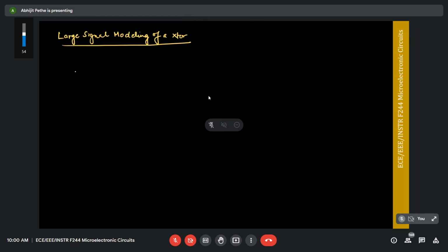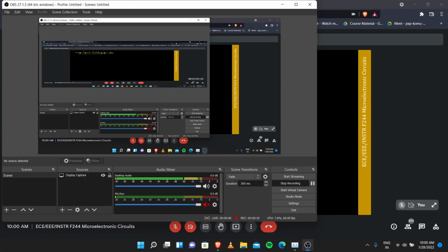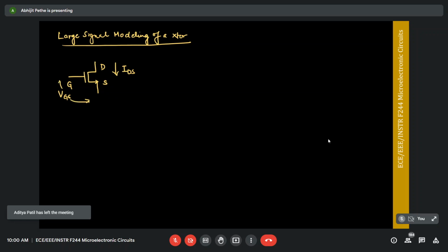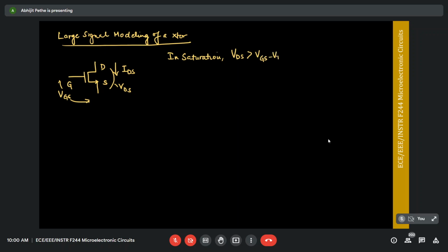Okay, so let's go back to saturation. When we had an NMOS in saturation, and this was VDS, right? So in saturation, what is the condition for saturation? VDS should be greater than VGS minus VT. Correct. So VDS is greater than VGS minus VT. That's not equal to; at the point where it's equal, VD sat is also in saturation.